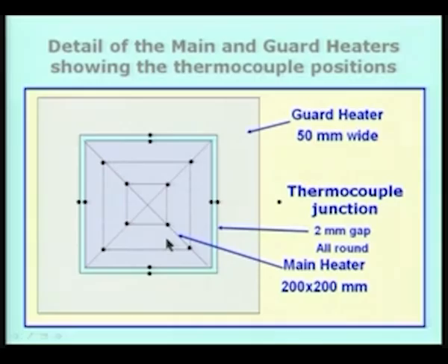Similarly, on the cold surface, the thermocouples usually are built in onto the heater, and they are not going to be attached to the sample. Sample is simply kept there, okay, and between the sample and the heater, you may give some kind of a surface treatment. You can make it very smooth and use some kind of a film of material of high thermal conductivity, so that the contact resistance is brought down.